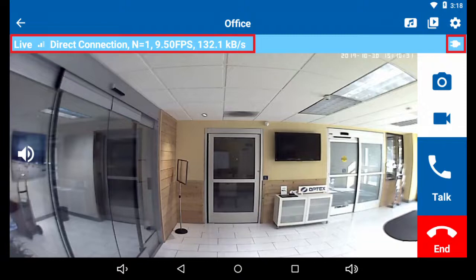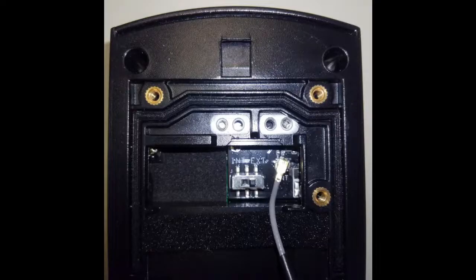The indicator to the right shows whether the DS is battery operated or hardwired. A common misunderstanding when wiring the DS is that the switch underneath is a power mode selection switch. That switch is the antenna switch. The switch should only be on EXT external if an external antenna is being used, as can be seen in this picture.